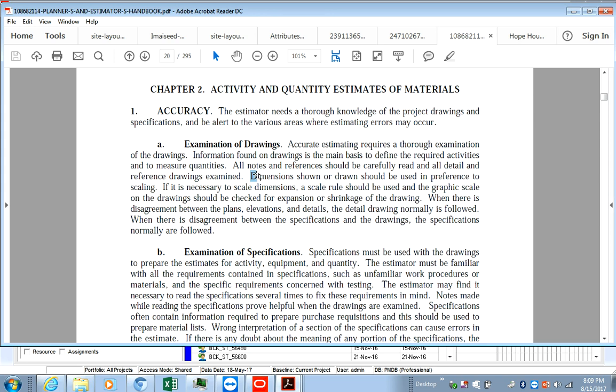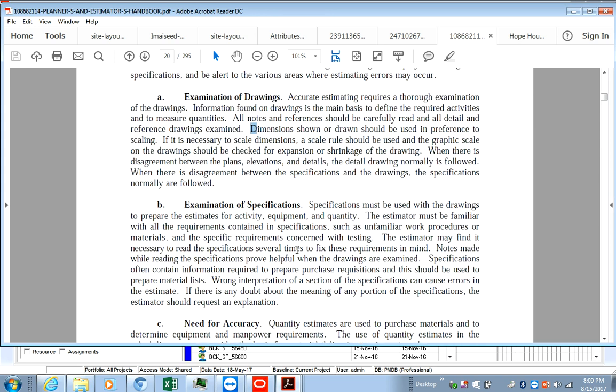say for instance the mechanical, electrical and plumbing guys will come in, but the specifications for where they're supposed to run their piping, run their containment, etc. isn't the accurate sizes, right? So say for instance you've built a lift shaft, but the lift shaft cannot actually contain the lift itself, or the specification for the width of the lift was a lot bigger than the specification of the lift pit that was dug in the foundation all the way up. You see, so dimensions, specifications, all of those things have to be done accurately and to the right scale, basically.